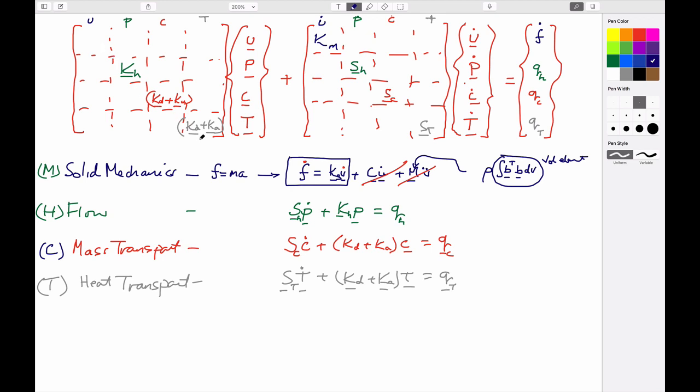And so our challenge would be that if we want to represent the simplest of these couplings, one simple coupling would be thermomechanical behavior. So the very simple idea, right? If you heat this up, it gets bigger. That's fine. Nothing changes. The stress doesn't change, but the strain would change because it would physically expand. If you heat it up and hold it and force it to not expand, then it'll build up stresses in it, and you can calculate what those stresses would be from the coefficient of thermal expansion and the modulus of elasticity of it.